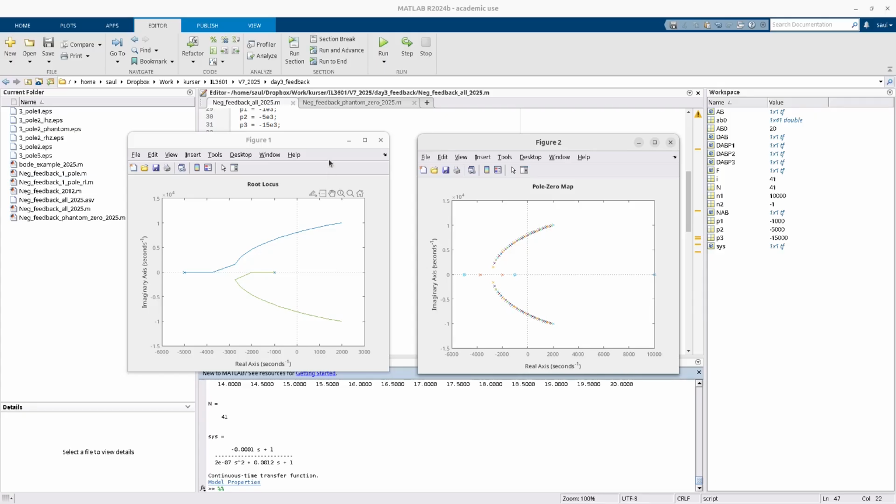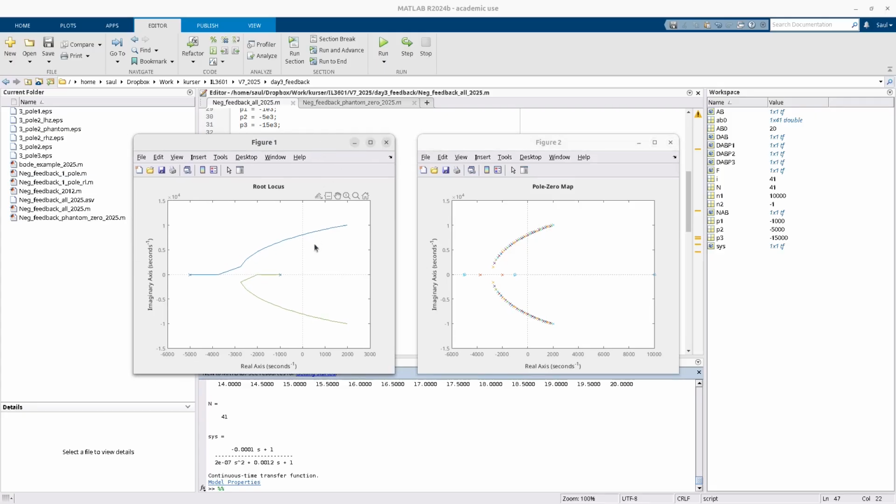Now what is the main idea here? In MATLAB we can have the root locus directly with this function. The one on the right, which is exactly the same information, is just extracted by sweeping the loop gain, which is something that we can actually implement in our circuit simulator, as we will see in the following lecture. So we can have in Cadence, with our circuit simulator, the same information that we have in MATLAB. We see that now these poles are on the right-hand side, they are unstable, so this zero has attracted these poles.